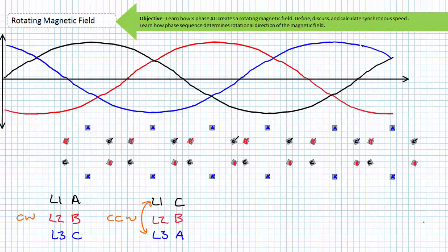There are those that say that there is a unified industry standard of interchanging line 1 with line 2, but I am here to tell you it is the wild, wild west. Be aware of alternate interchange configurations, but be aware the alternate interchange configurations are accomplishing the same task. For the purposes of this reversal example, let's go with the industry standard and swap L1 and L3.